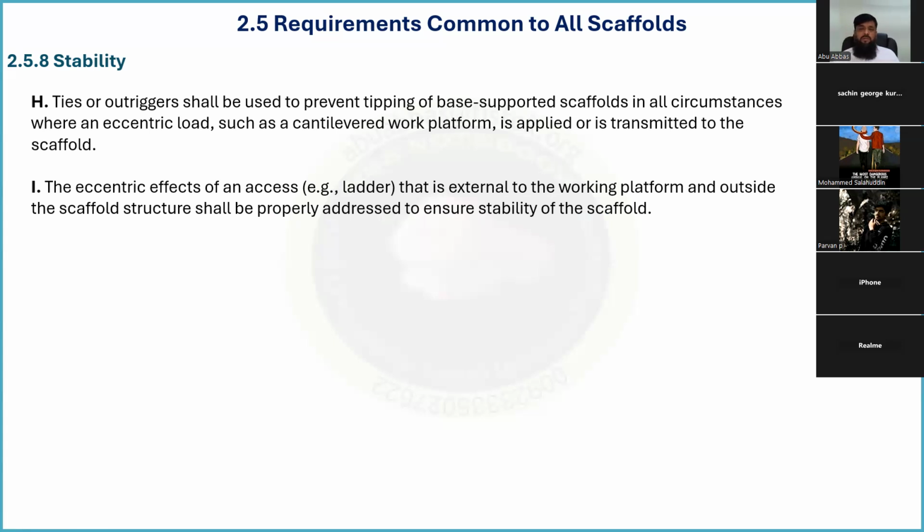The eccentric effect of an access ladder, like the ladder we use that is external to the work platform and outside of the scaffold structure, shall be properly addressed to ensure stability of the scaffold.